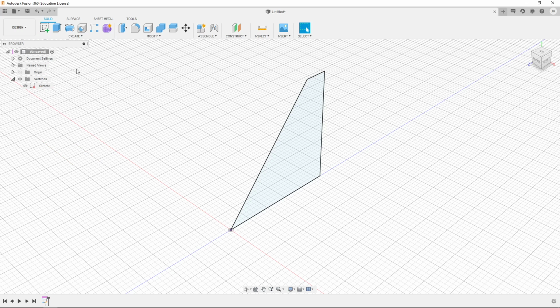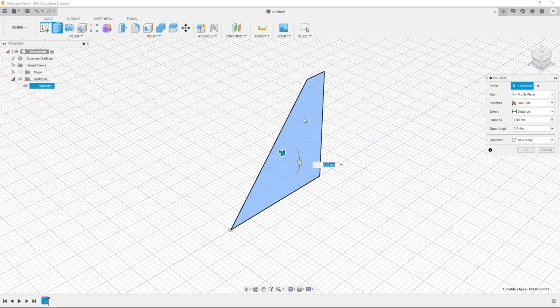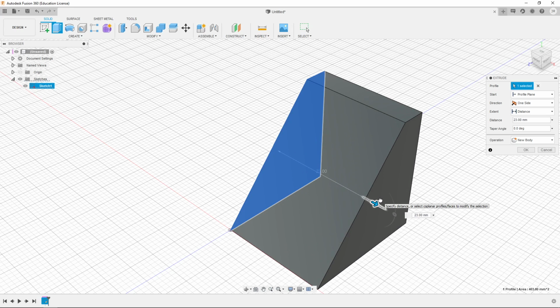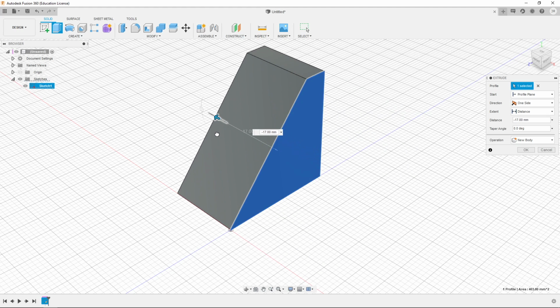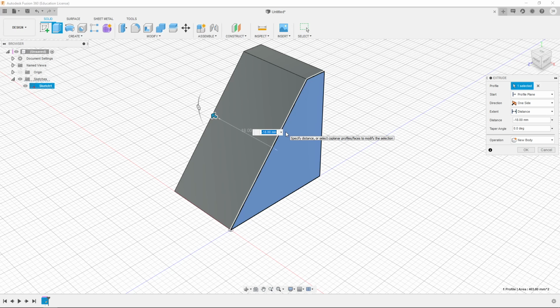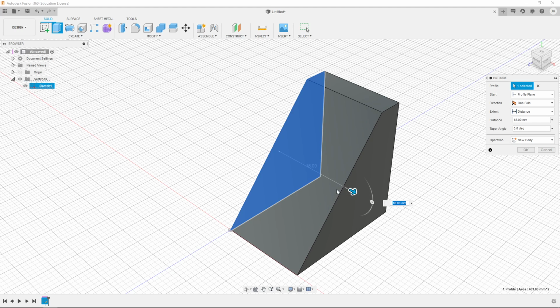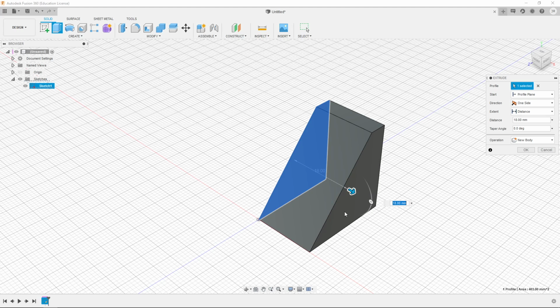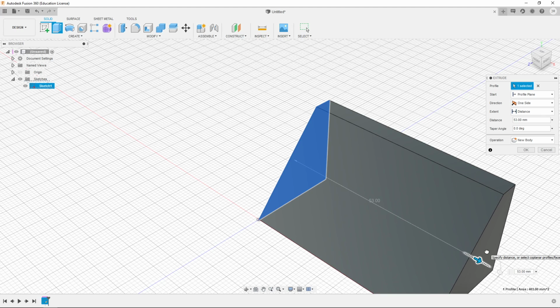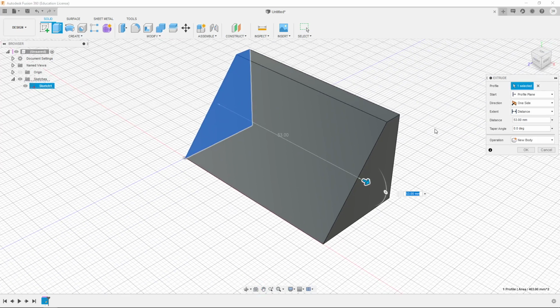So we're going to choose this button. As soon as I click it, since I had this selected, it turns blue, and it gives us this little arrow. On the right side, we have the extrude menu. There are a lot of options we're going to look at. If I just do it manually and drag this, we can see that it pulls it out in 3D. I can go either direction, and it tells me how far I did it. If I go backwards, it's negative 18 millimeters, but the negative is just the direction, not the actual magnitude. Similarly, if I go this way, it's positive 18 or whatever it might be. We said 53 millimeters, so I could go all the way to 53. That's not unreasonable, and that's not bad. But I want to try some other things.